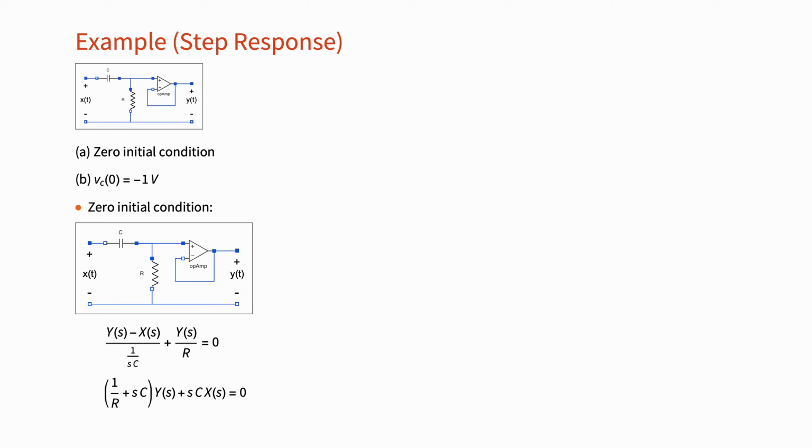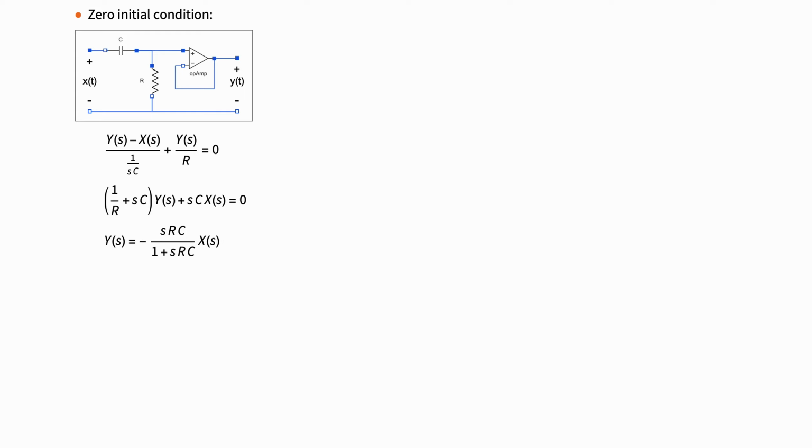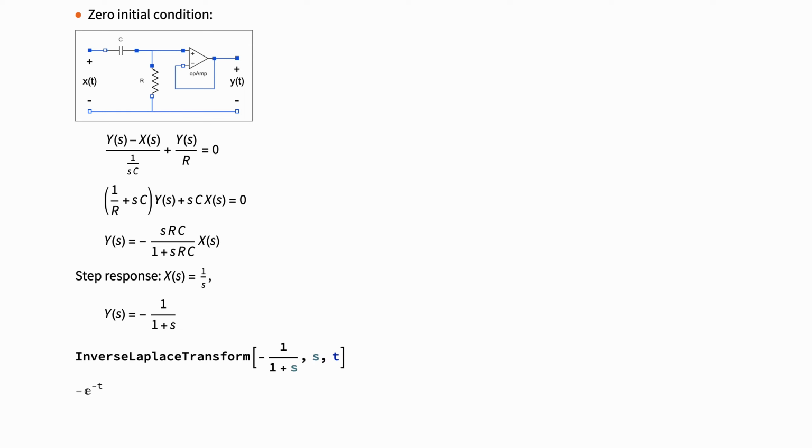Simplifying the equation and solving for Y(s) and replacing the values for the resistor and the capacitor and 1 over s for the step input X(s), we get the Laplace transform of the output as shown here. And we apply the inverse Laplace transform to get the step response in the time domain.